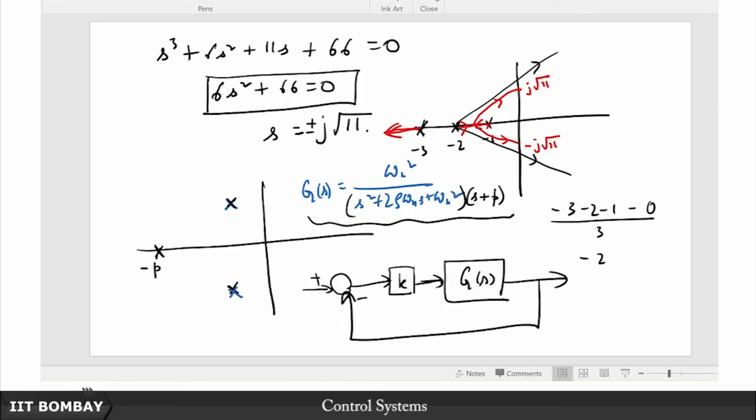We want to understand how the root locus behaves, and not just that, the root locus will actually tell us what effect this additional pole has on the stability. So notice very carefully here, what can you say about this? There are 3 poles, no zeros. What can we infer about such systems?